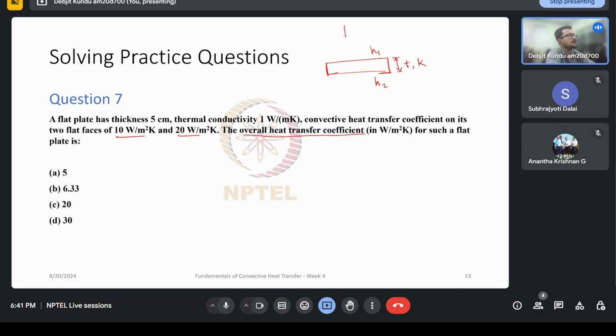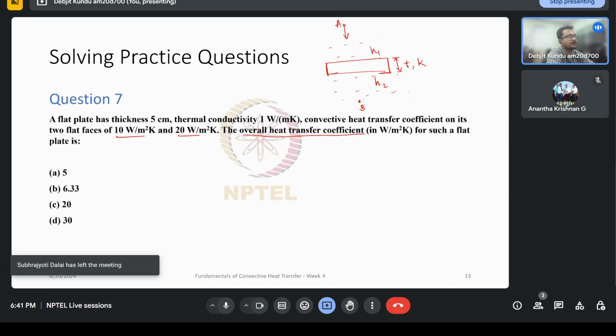So given I want to transfer heat from this end, let's say point A, to some point B over here, there are different fluids in between where convection takes place. So from this point A to B, what is the overall heat transfer coefficient? If you look at this in a different way, this is exactly like how you solve for resistances, analogous to an electrical circuit.